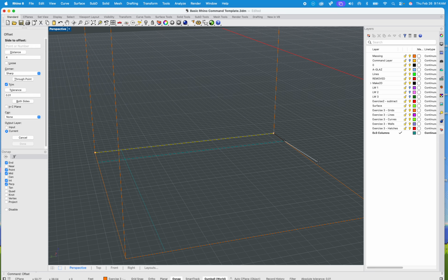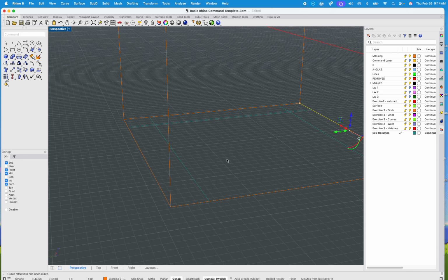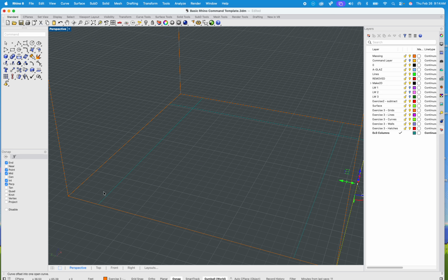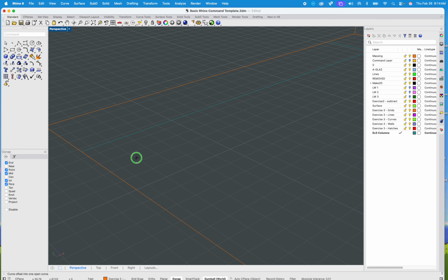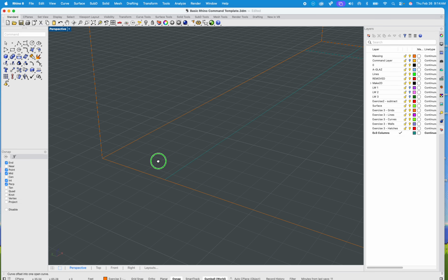Quite literally I can start to potentially make these stairs. Now, if you're viewing it right now, it's kind of the plan view, right? It's been flattened on the ground. And essentially I need to start making a necessary profile. In my case, we're going to use 6-inch risers and 12-inch treads. Now, in real life, you would use 7 1/4 and 11 3/4, right? So, don't get me wrong, we want to be architectural, but for those of us who haven't taken any design courses, you wouldn't necessarily know that yet. But to make it simple, we're going to go with 6-inch risers and 12-inch treads. That makes the math a little bit easier.